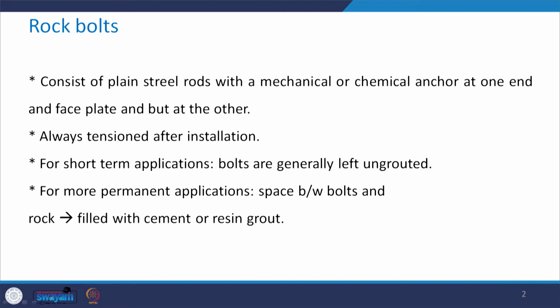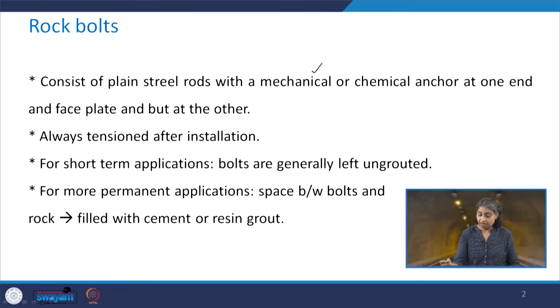Basically, these consist of plain steel rods with a mechanical or chemical anchor at one end and a face plate and butt at the other end. These are always tensioned after installation. This means that once you install it, from the other end you tension these bolts.